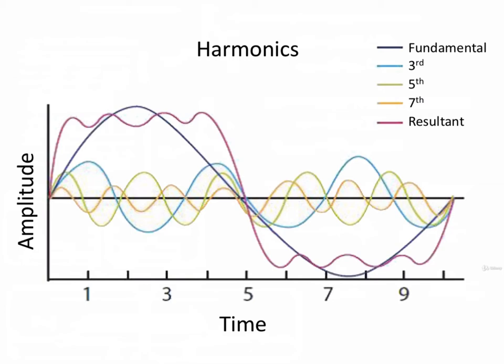And in order to analyze this, we have a system of doing that called Fourier analysis. However, just an understanding that complex waveforms, if repetitive, are made up of the fundamental frequency plus integral harmonics or multiples of the fundamental component is what matters here.